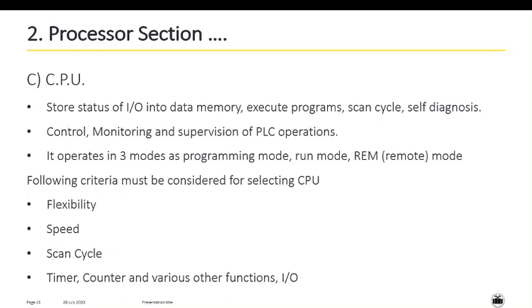Nothing will be functional. Only we can connect the external PC or device to the CPU, and you can load the user program into the CPU. Okay. In the run mode, second mode is run mode. In run mode, what happens? You cannot program the PLC, but whatever program we have written in the program mode, that program will be run by the PLC. Okay, so in programming mode, other modes will not work. In run mode also, other modes will not work.